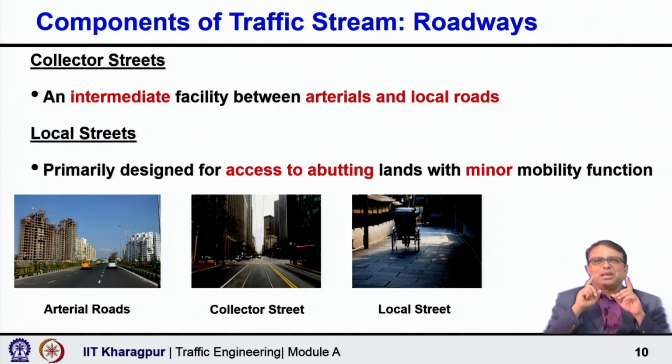So, if out of 100 the majority is accessibility, the mobility cannot be more. As I said, remember, accessibility plus mobility together may be 100%. So, if we increase one, or if we want more in one component, we have to compromise on the other part. If we try to achieve both, then the conflict will happen, and road safety issues will come up more and more.